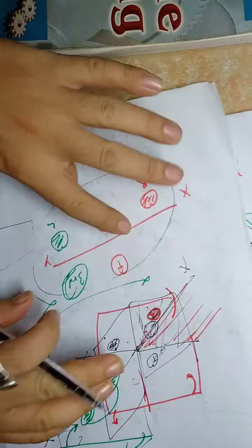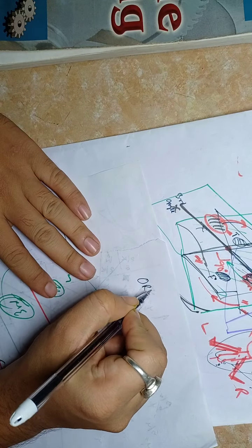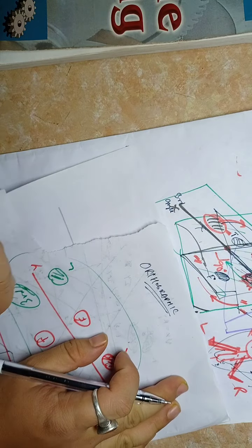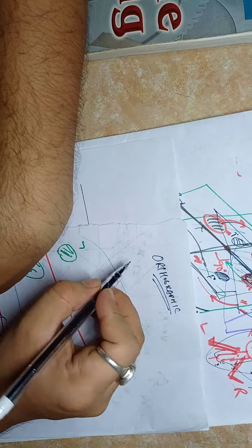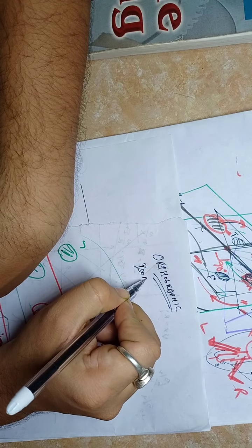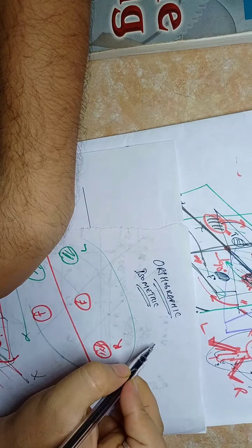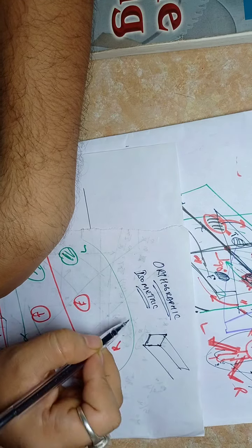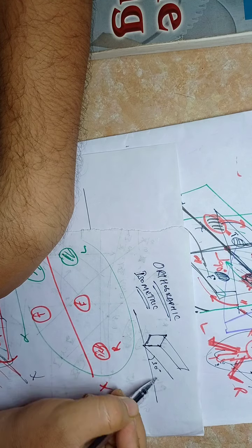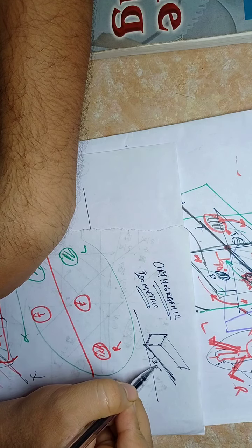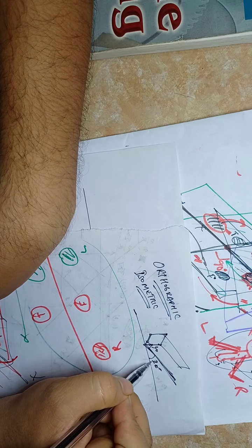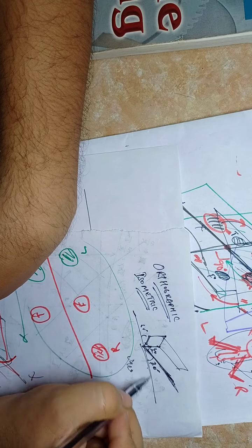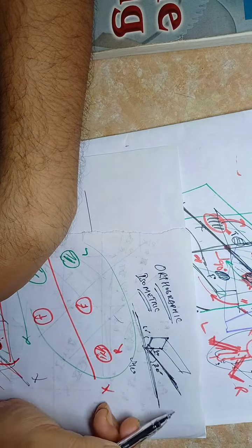Okay, before that, let me tell you, orthographic projections are something that we are going to draw here and everywhere in your drawings. There are 3 more projections. Then isometric projection is there. You have understood what isometric is. Isometric is when we draw any object at an angle of 30 degrees. One of its edges will be at an angle of 30 degrees, and this edge will be 90 degrees. So this is 120 degrees, 180 minus 120, this will be 60 degrees. So one of the edges must be kept at 30 degrees to this line. Okay, this is isometric view.